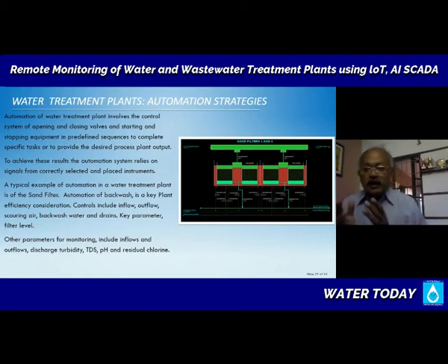And in a water treatment plant where you have 15, 16 sand filters, for instance, you will not backwash them all simultaneously. So you could go cyclically, 1, 2, 3, 4, 5, do an entire backwash cycle, one filter to another. So there is an automatic process for backwashing one sand filter. Then once that is completed, the sequence can jump to the next one, and then to the third and the fourth. Like that, you continue and you completely backwash your entire system. That is quite often in our country a very manual process, but that is something that can be very easily, efficiently automated.